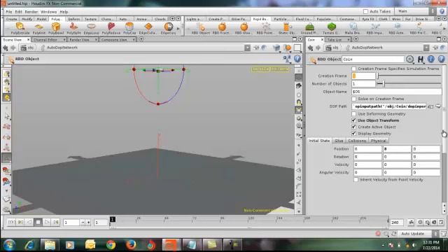I'm just going to come here and write if $f. $f is basically your current whole frame. For example, if the current frame is 1.56, it will return 2. So current frame is $f. If $f modulus 10, that means if I divide the current frame by 10, the remainder I get, that is what $f modulus 10 returns, is equal to 0. That means I am checking if my $f is a multiple of 10.